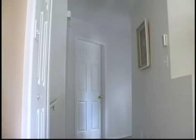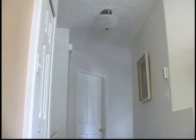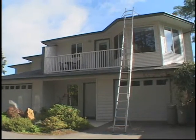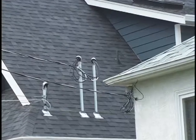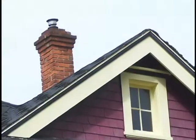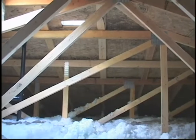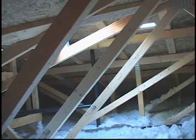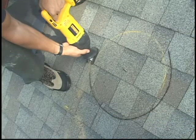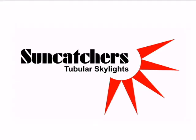First, look at the room you are trying to enhance and decide where the skylight should be located to best utilize the light. After you have the approximate area in mind, go outside and look at the roof line. Are there hips, valleys, vents, or other objects that might interfere with the tubular skylight's placement? Next, go into the attic and determine if there are any electrical, plumbing, cross trusses, or anything else that might change the location of the skylight. Never cut trusses or rafters unless qualified to do so.